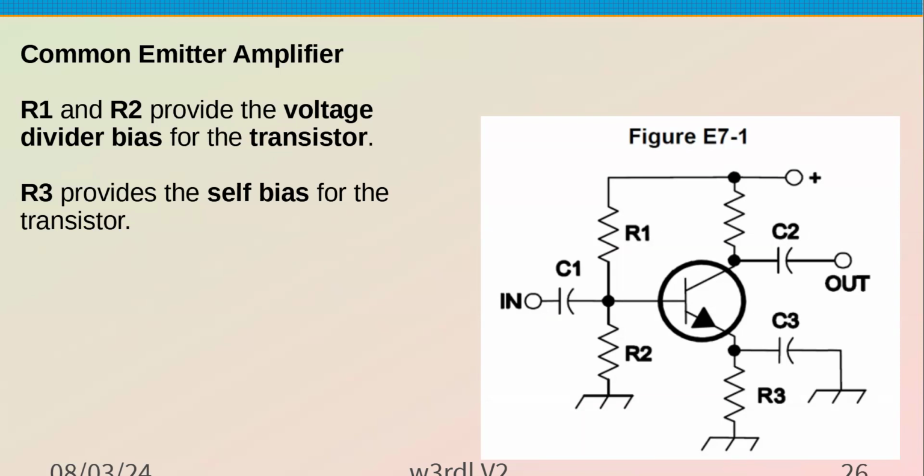So you get the base bias voltage set by this R1 and R2 resistor combination. So it's going to be a voltage divider based on your input voltage and supply voltage. So if these were equal, say this was 12 volts, it's going to be 6. It's going to be a little bit high. But that's how you set the initial bias voltage to determine where the operating point is going to be.